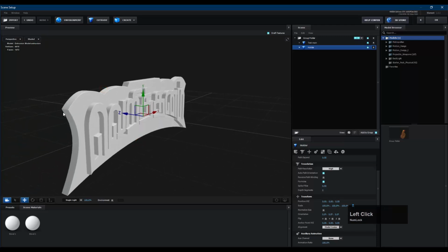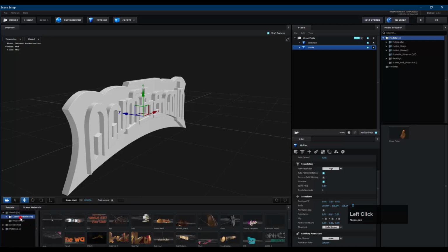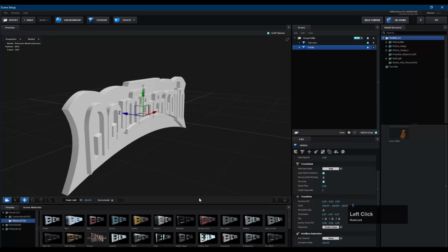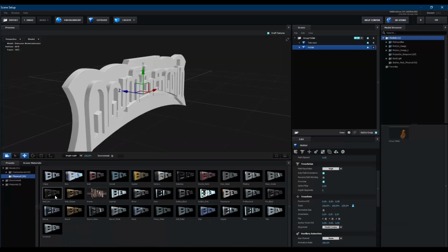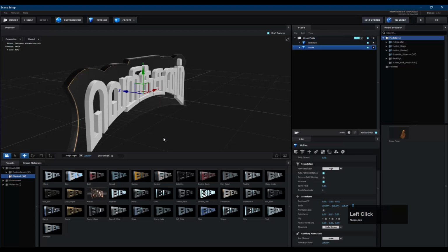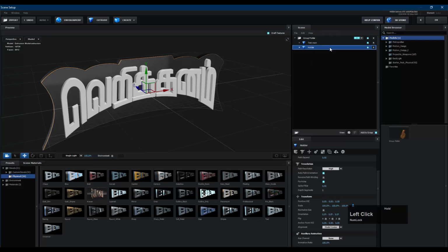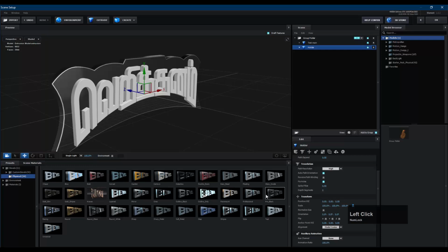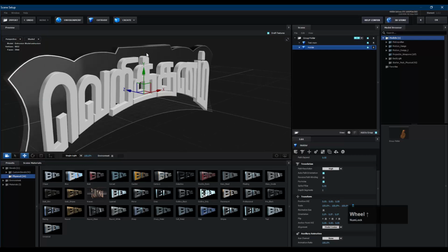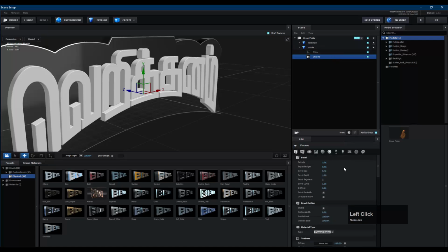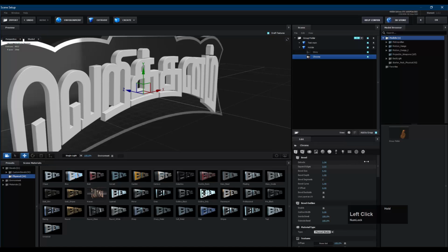Let's select this and go to presets and check levels. Go to physical. Let's try applying a preset and check how it looks. I think this one is perfect. Pro black. So let's just stick to this one and then select this chrome material and click expand edges in order to expand this one. So I think this is working.